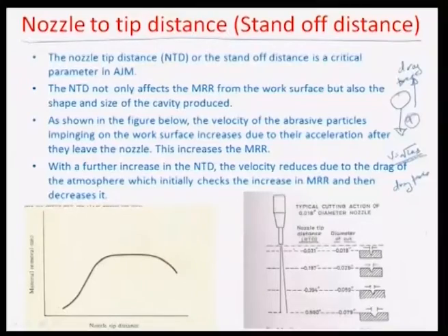Therefore, at low nozzle tip distances, an increase in the nozzle tip distance would result in an increase in the material removal rate.